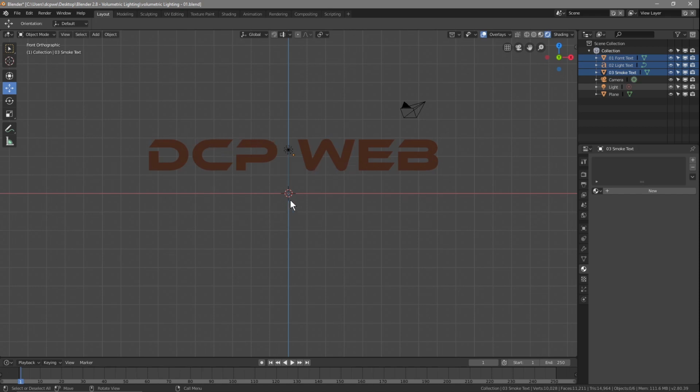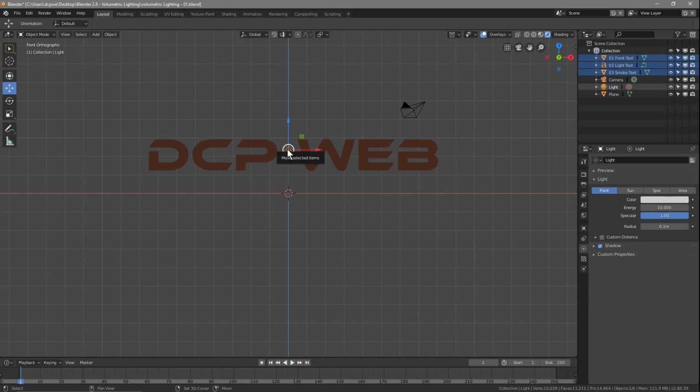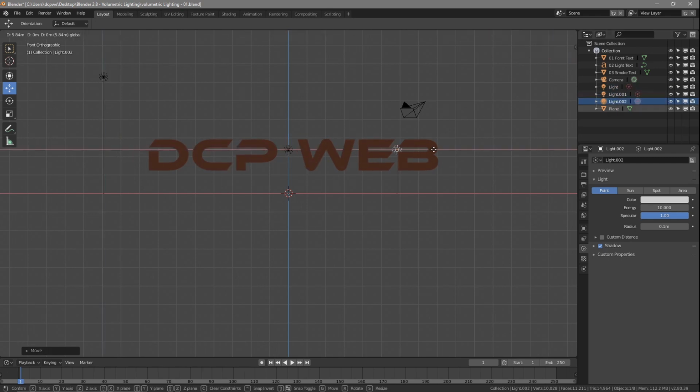We'll see what happens. We'll take this light source. We'll press Shift and click on the light source in here, right? This is the light. We'll press Shift D to duplicate it once, and Shift D again to duplicate it twice. So we've got 3 light sources now. The first one's going to stay in the middle. This one here, we're going to drag and move it up to the left. And then this one here, we're going to drag and move it up to the right temporarily.